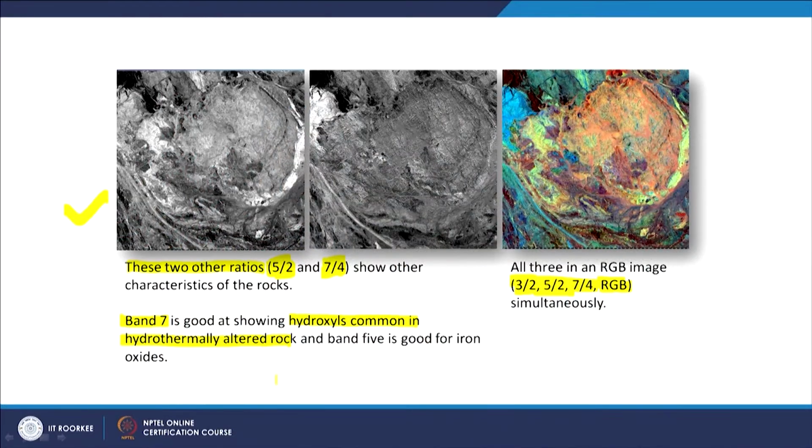So, a normal false color composite image will never give you such results. A single two-band ratio will always create a black and white image. Here, using 3 band ratios and giving an RGB scheme, an additive color scheme, one can create beautiful outputs to discriminate different objects, different features, different rocks, different minerals very clearly, very convincingly. So, that is the advantage.